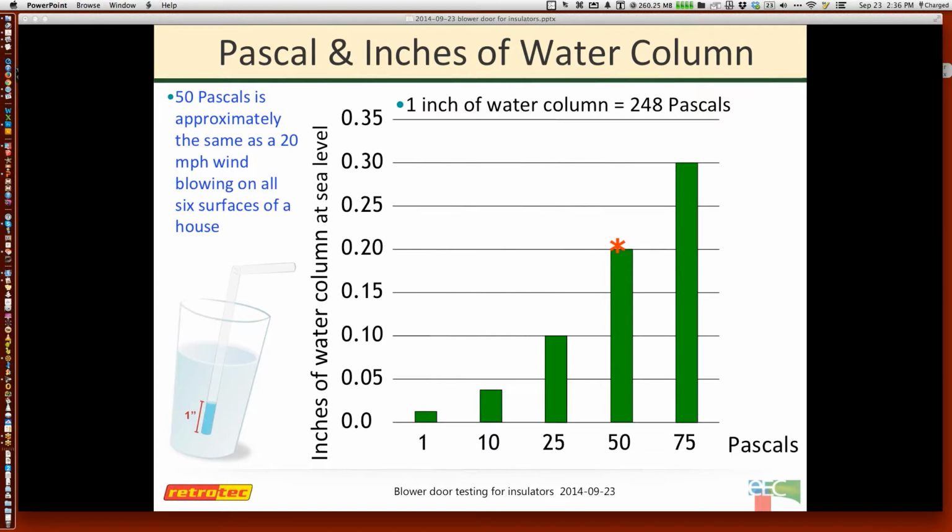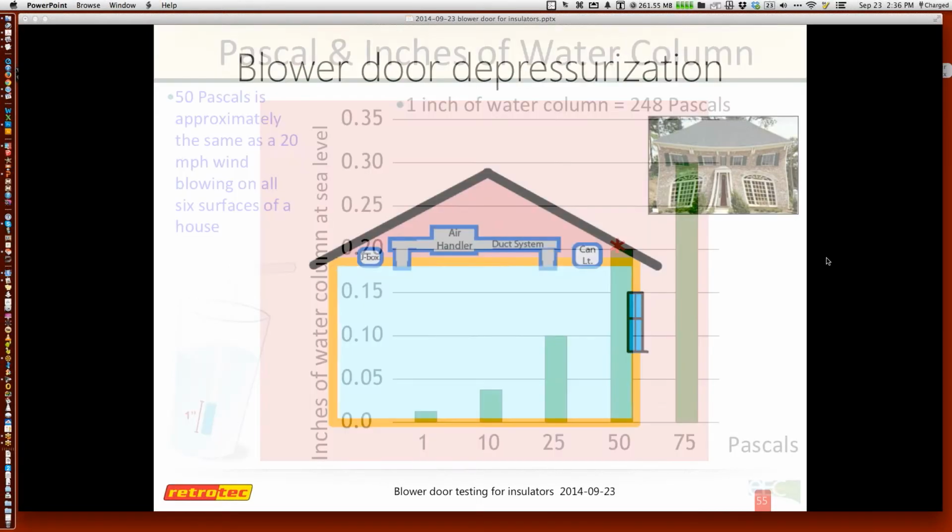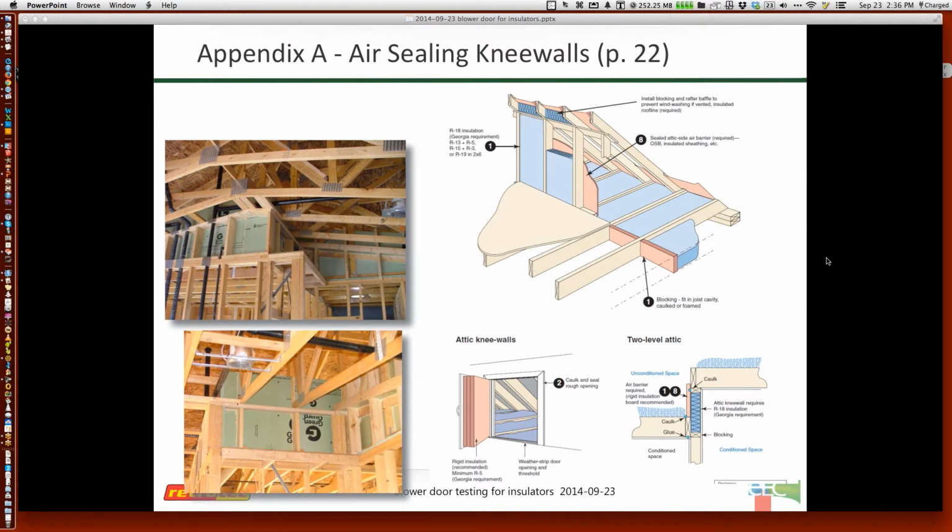Someone asked, which kind of made sense just where I was at that previous slide, so let me just go back. Someone asked about factors to consider for conducting a pre-drywall blower door test. So what you're needing is almost the same things that are needed for the insulation contractor to show up. Usually you're looking for a ceiling in most cases, unless you're doing spray foam on the roof deck. But in general, you're looking for walls to be open, and you're looking for a ceiling in place.